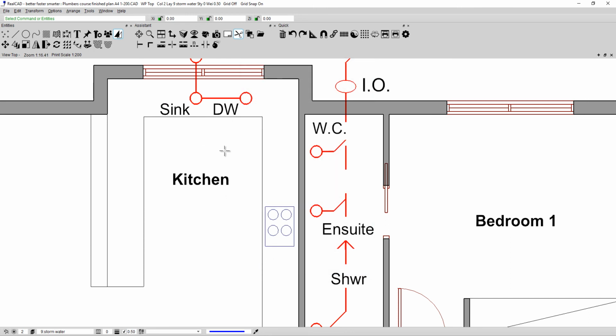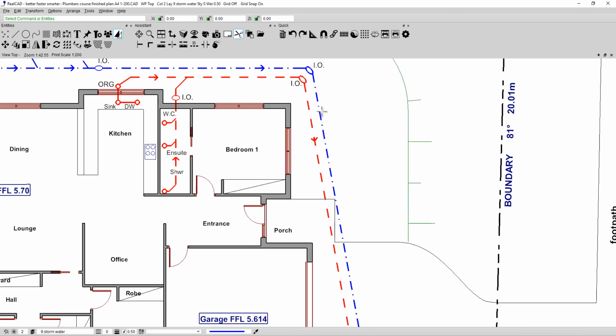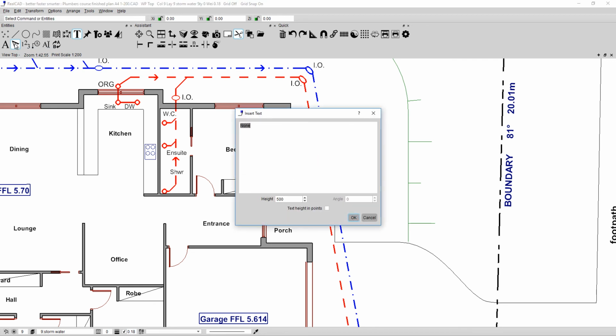Go around the whole drawing and add all of the text that you see. You are going to be challenged by the text along this line because this is an angled line. And the only way to do this type of text effectively is either to copy a piece of text over and use the rotate command as you did with these types of symbols, or perhaps better still, clone the text properties. Okay, so you've got the right colors and things going on, and go to the text command, come up here to the text by rotation, an angled A, and type in